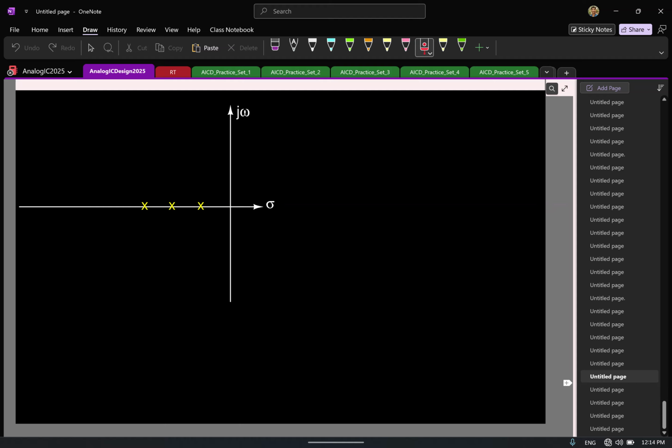Let's figure out the portion on the real axis. So can I have the root locus lying here? I can have here. So which means I can have only here. Then, and I know for a fact that the closed loop poles should terminate at infinity. I see one of them is already going to infinity along this line. Correct. So which means I should figure out what happens to the other two.